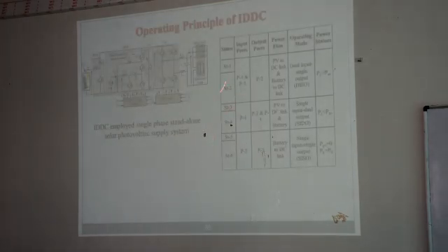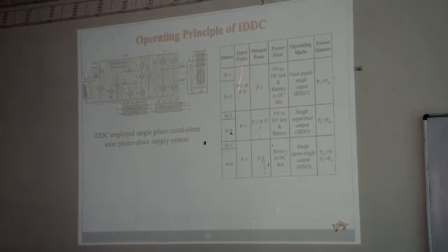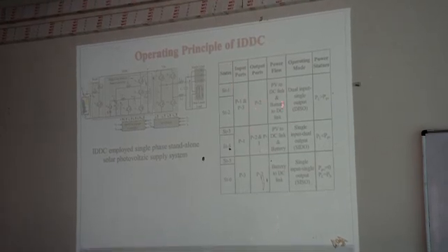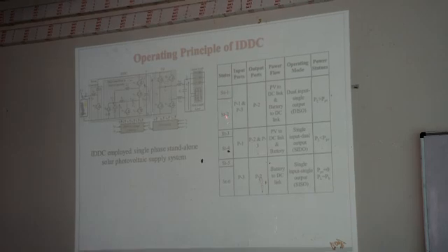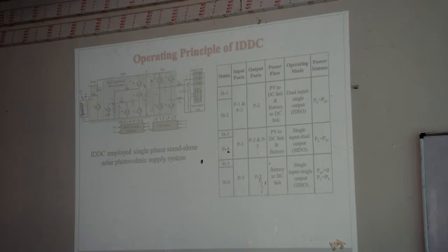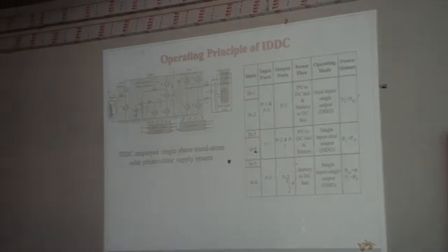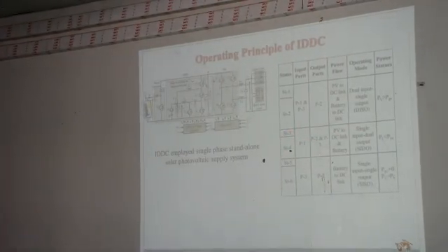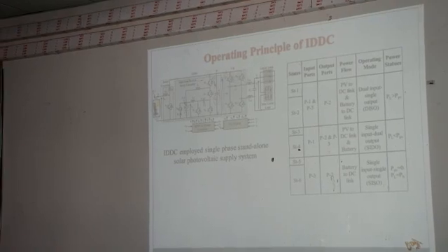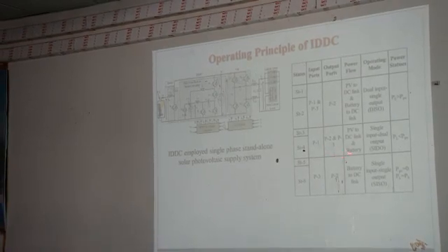According to the status of power available, you have different input ports and output ports. When these two input ports are available, you feed the output port, state 2. When 1 and 3 are available, then you feed power to the output port. The output port is your main DC. In this case, port 1 is available and you are feeding power to your load and to the battery, meaning generation is in excess, so we give this power to the load and your energy storage system. In the third case, solar is not there and port 3 is feeding power to the DC port.